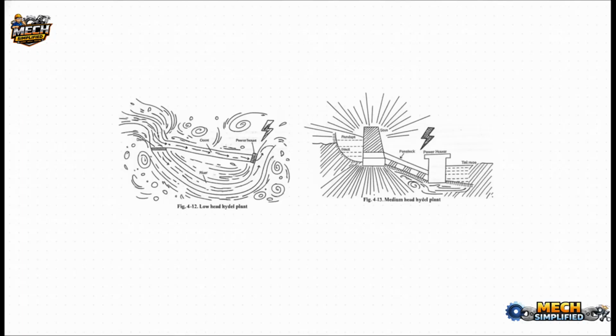And it all comes back to that head we talked about. On one side, you've got a low-head plant, often called a run-of-river plant. It just diverts some of the river's natural flow. But on the other side, a medium-head plant uses a big old dam to create a really significant height difference. That means way more pressure, way more power, and a lot more control over when you generate.